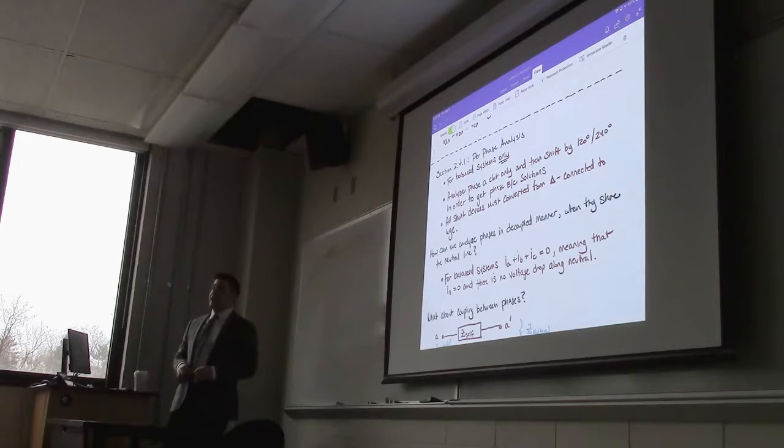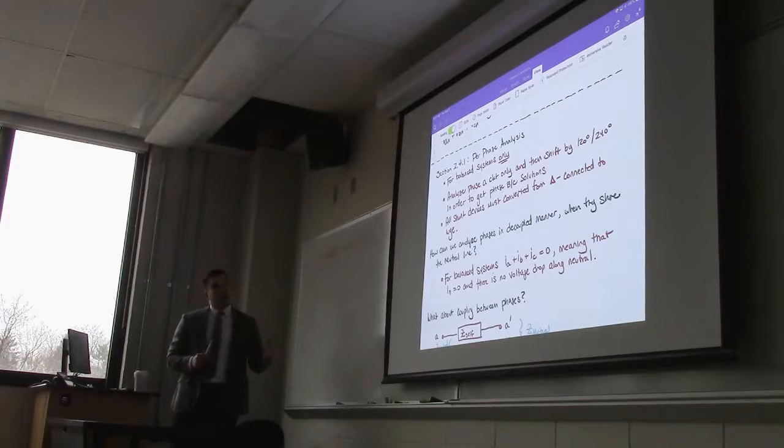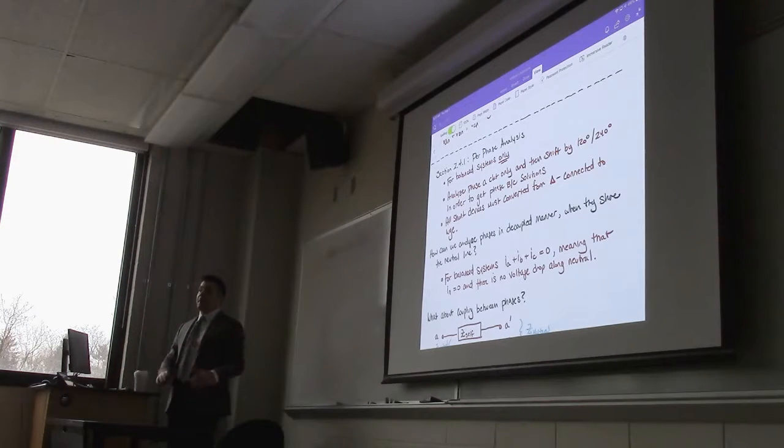Which means that if all the voltage sources, all the transmission lines, all the loads, if they all have the same values and the same structure, then we'll just forget about phases 2 and 3, or phases B and C, and we'll solve phase A, and then we'll just copy the values over with the appropriate shift. What's the shift? Let's say you have a voltage waveform. What's the shift? 120 degrees. 120 degrees, right?